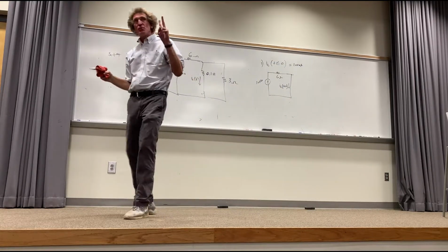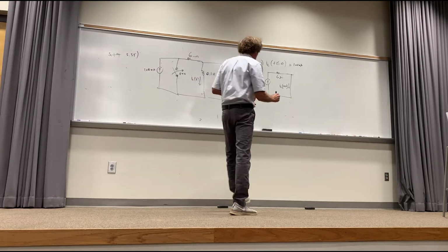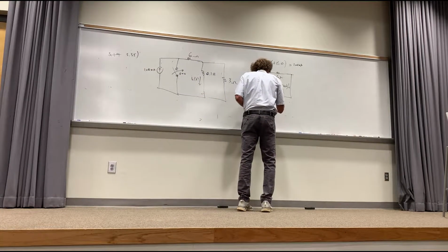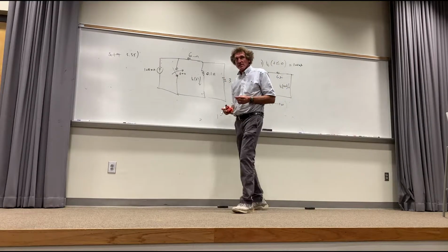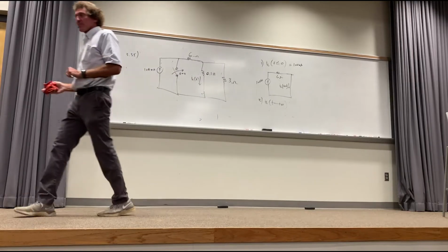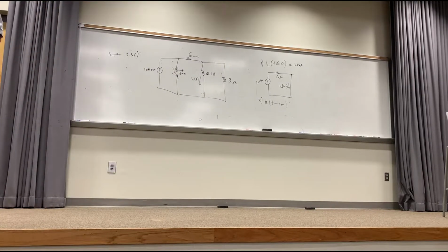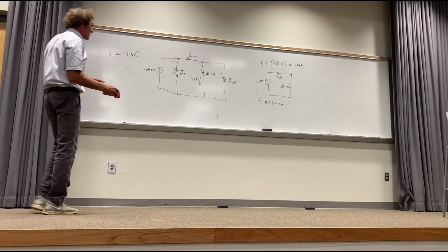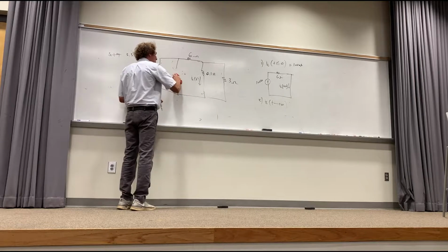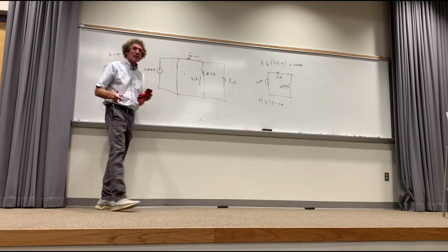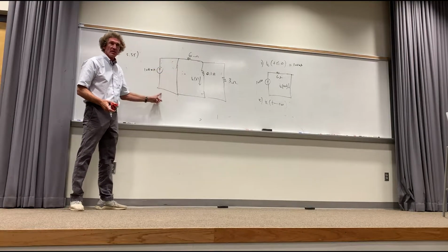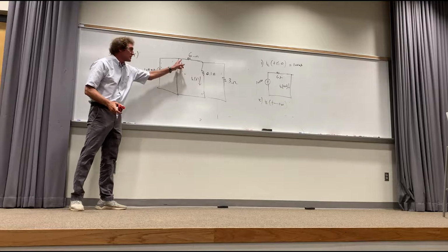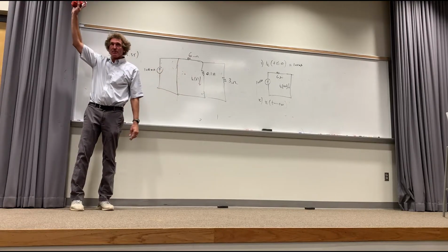Now, part 2, we need the current as t goes to infinity, right? Correct, class? I'm going to slow down, make sure you see this. All right, so now the switch is going to get thrown. It's going to flip states. When it gets thrown, I'm going to draw right here. This becomes a short, doesn't it? When that's a short, how many see that all the current's just going to circulate here? There's going to be no voltage difference between these 2 points. Give me a show of hands if you see that.